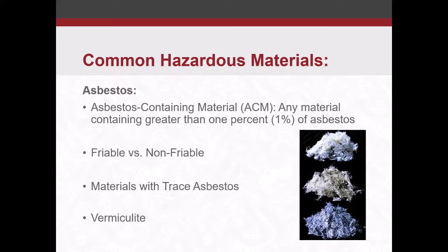So there's an OSHA standard that describes what to do with asbestos materials, and that does include trace asbestos. So sometimes in a design, we'll have awareness notes for trace asbestos materials, but other times, it may just be better off to allow the client to set that up so the abatement contractor takes care of those materials so that no one else has to deal with them later. Other contractors may not be well suited to deal with those materials, so it might be more efficient just to schedule as abatement, even though it's not necessarily needed per the regulations.